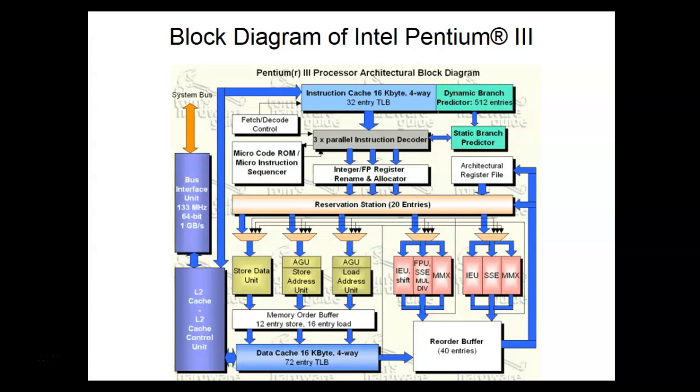It was looking for that module on the right hand side, and we had taken it off. It knew something was missing in its hardware configuration. So we plugged it back in there as a stopgap, but we could have gone ahead and upgraded the I/O on it. So they're working fine now. Are we okay?